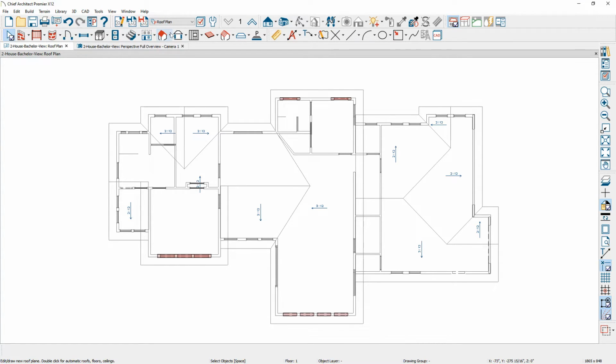One of the tools that we have is called the gable roofline. If you come in somewhere near the edge of that wall and you draw the gable roofline, it will automatically create a gable for you. It's a handy tool if you're drawing it over an entryway, against a flat wall, or maybe over a window. Let me show you another way to do that because I want this to be exactly symmetrical.